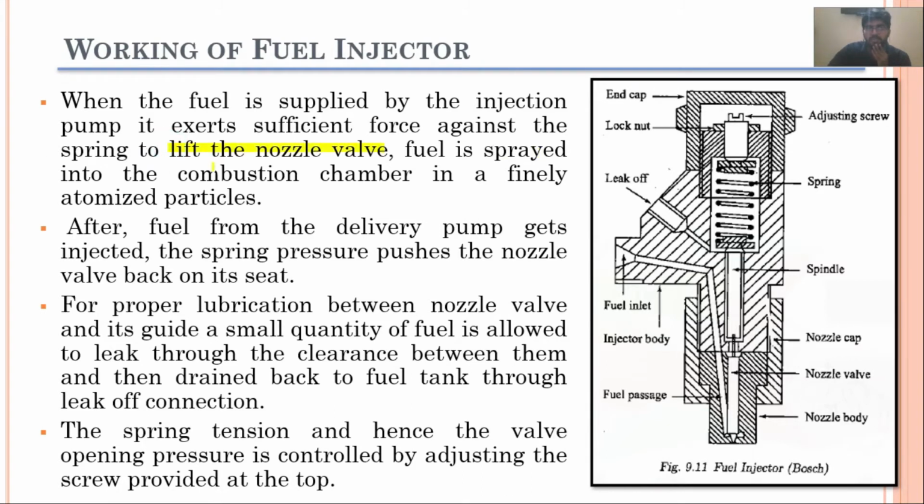Fuel is sprayed into the combustion chamber in a finely atomized form. The fuel from this inlet passage will accumulate here and apply a sufficient amount of force so that this needle valve gets opened, and then this fuel will be injected into the combustion chamber.